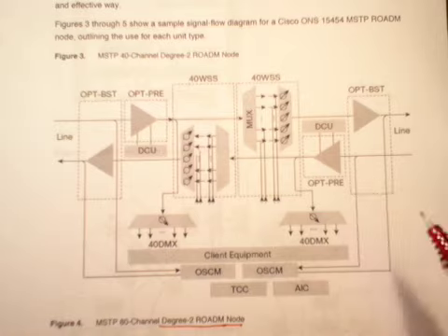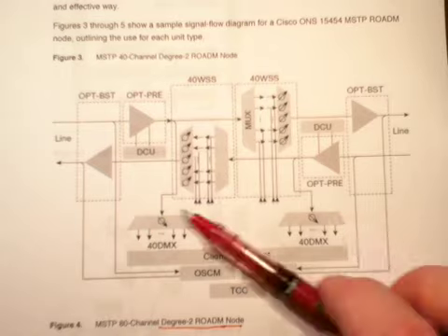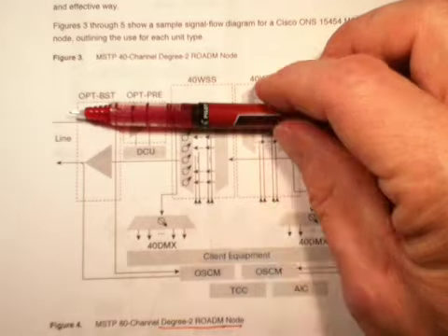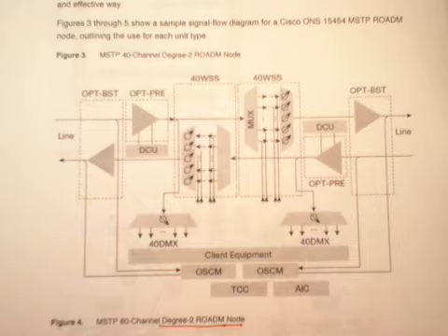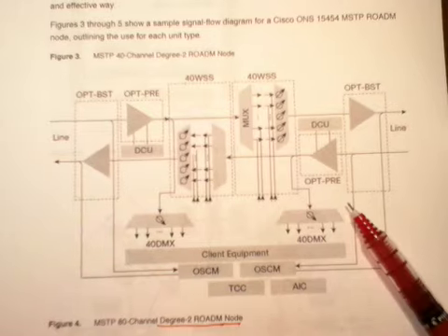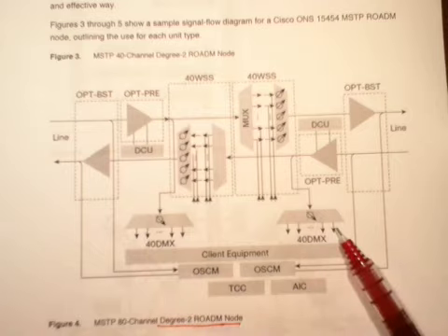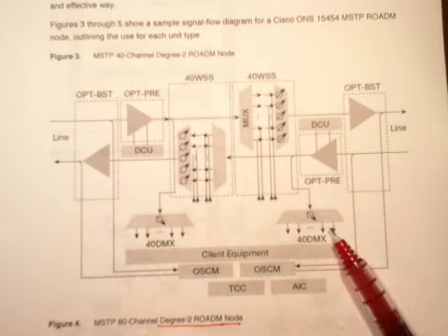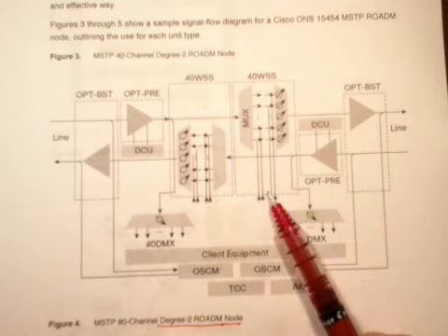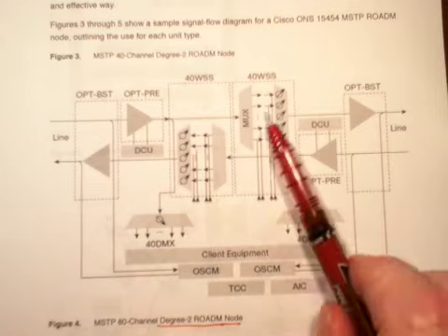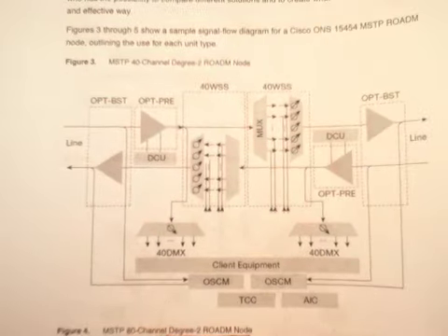It's a great thing. You can drop any combination of the 40 channels you want, and then add in new information onto those channels, and it works in both directions. The main limitation of this device is that each of these output fibers from the demux is channel specific. You can only get one wavelength out of those fibers. Same thing on the add channels. You have to add the right wavelength on the right piece of fiber, or else it won't work. Okay, so hopefully that helps describe these things.